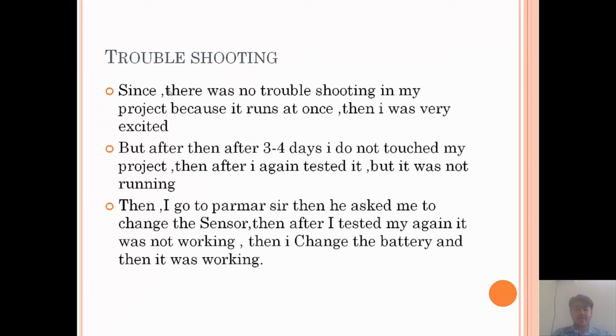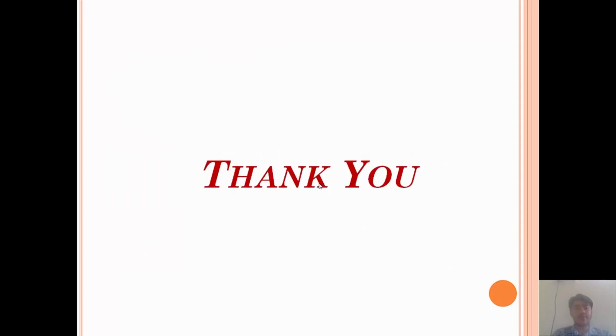Now troubleshooting. In this project which I built, it ran at once, but after 3 to 4 days of not touching my project, I tested it again and it was not running. Then I went to my guide and he asked me to change the sensor and test it again, but it was still not working. Then after many trials and errors, I found that my battery was fully discharged. So I purchased a new battery and the project was running well again.